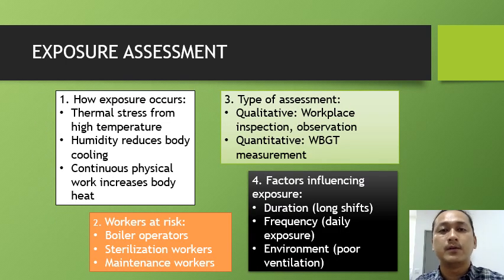Exposure assessment. Exposure to heat occurs through thermal stress, where workers are affected by high temperature and humidity. The body cannot cool down effectively. Workers at higher risk include boiler operators, sterilization workers, and also the maintenance staff. We can assess exposure using qualitative methods like observation and walkthrough surveys, and quantitative methods such as WBGT measurement. Factors like long working hours, daily exposure, and poor ventilation increase the risk.